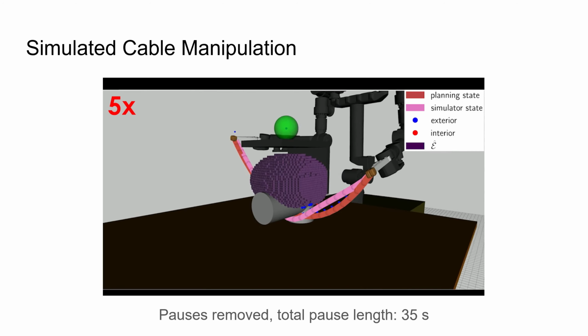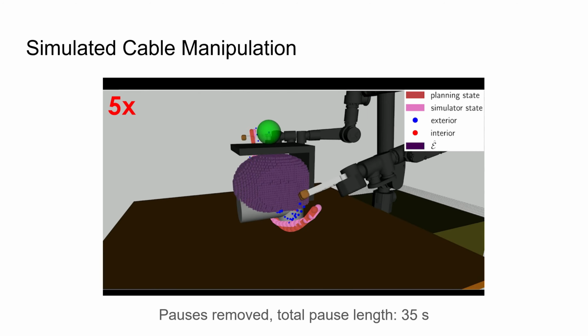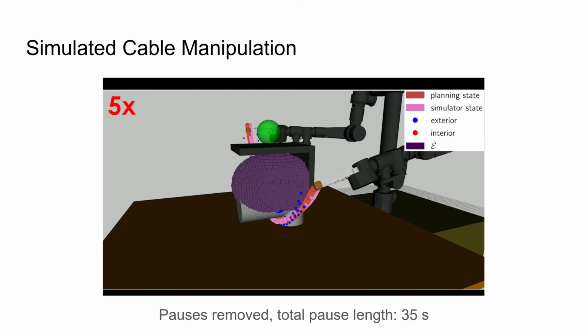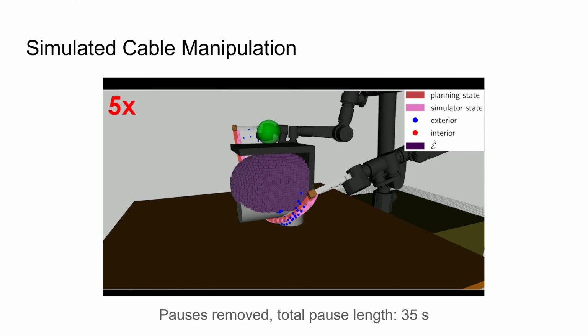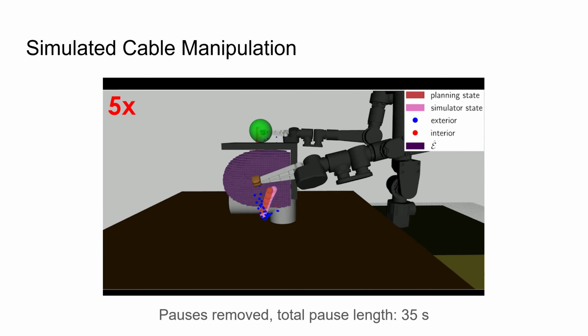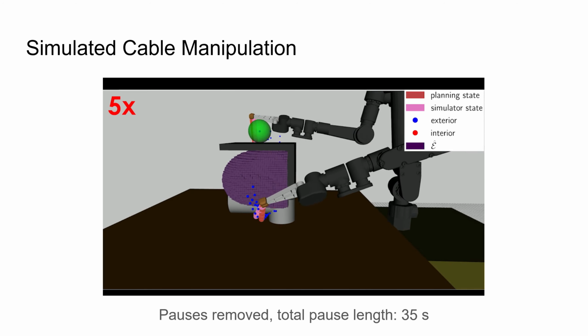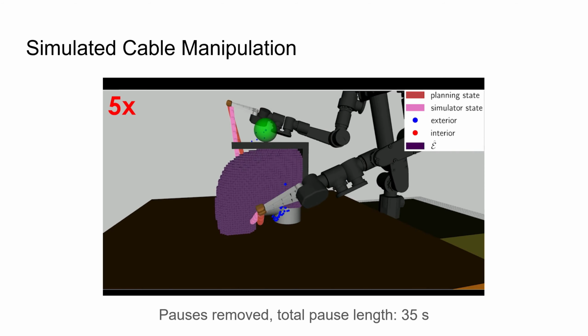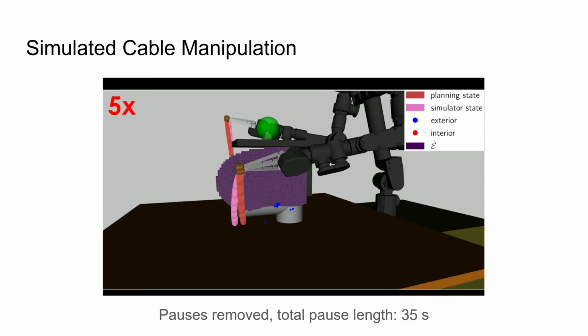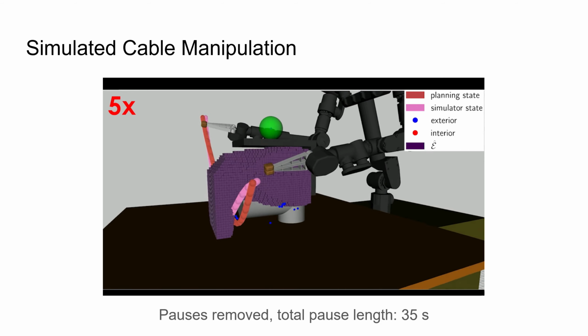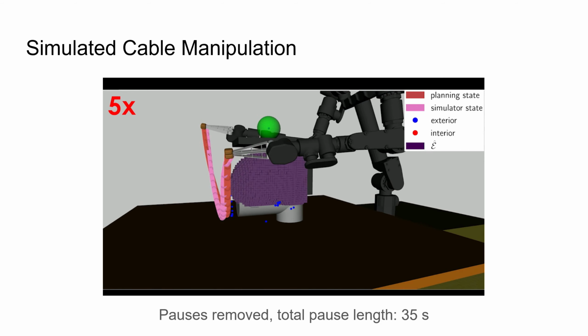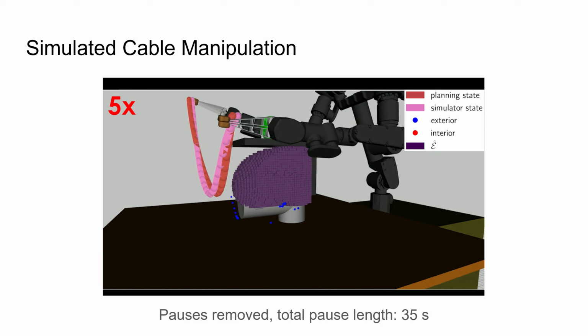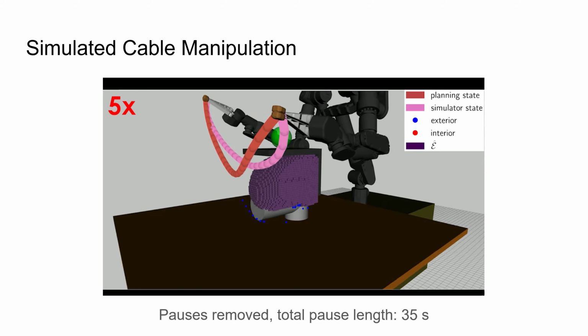There is a high degree of occlusion caused by the barrier in between the robot and the body of the hook. This can result in the cable state estimate penetrating the surface estimate, which can interfere with our controller that seeks to avoid the surface. We constrain the surface to avoid penetration. We use a vision-based estimate of the cable state for planning, shown in red. While this leads to state estimation error due to occlusion, COGIS is still able to complete the task successfully.